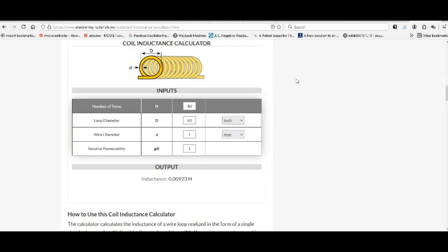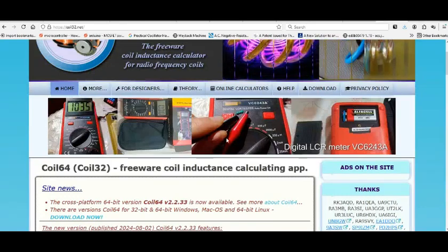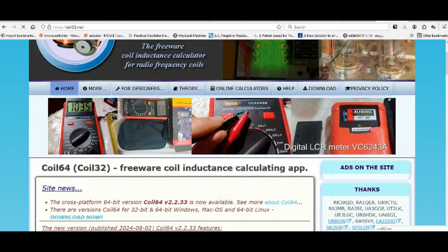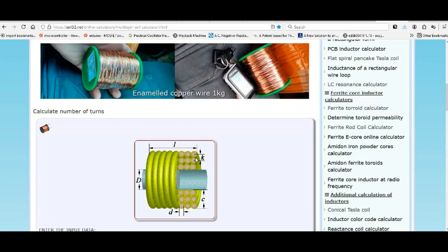But to wrap this up and bottom line it, we want to get rid of the proximity effect. If you have a multi-layer coil, you could do that, but you would want to space this layer from that layer, so each layer spaced apart, and then each winding spaced apart. And even with the 3D printer, it's a little bit of a bear to figure out how you would easily do that without making the winding an ordeal.